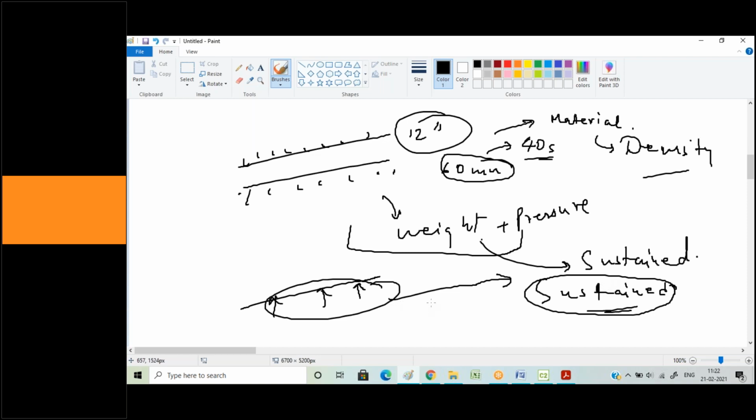But when you come to a Caesar guy and you say, okay, I've used this number of supports and my loads, I guess this will work, he will say that this is what you have done only for sustained. How about for the expansion and the operating case? How about for this too?